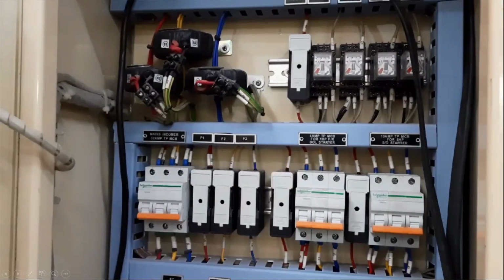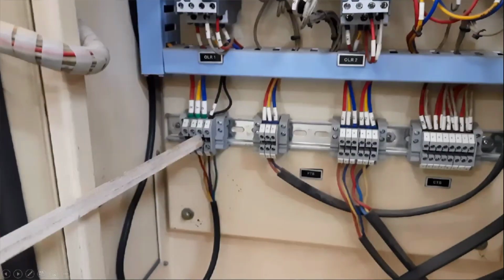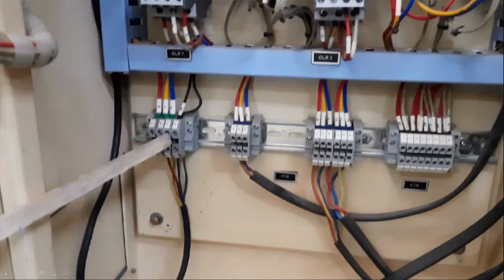If we see at the bottom, this is the incoming supply. See, a panel is basically a device which comes between the supply and the motor, because the panel is the one which is going to control the performance of the motor. So this is the incoming terminal. We have to give 3-phase supply to this panel, and from this panel there are 2 motors which we are going to drive. These 3 terminals are for the direct online motor. We are going to use a 1 HP motor for direct online, and this is for the star delta motor. The star delta motor is of 2.2 kilowatt. Now all these are basically the controlling circuitry.